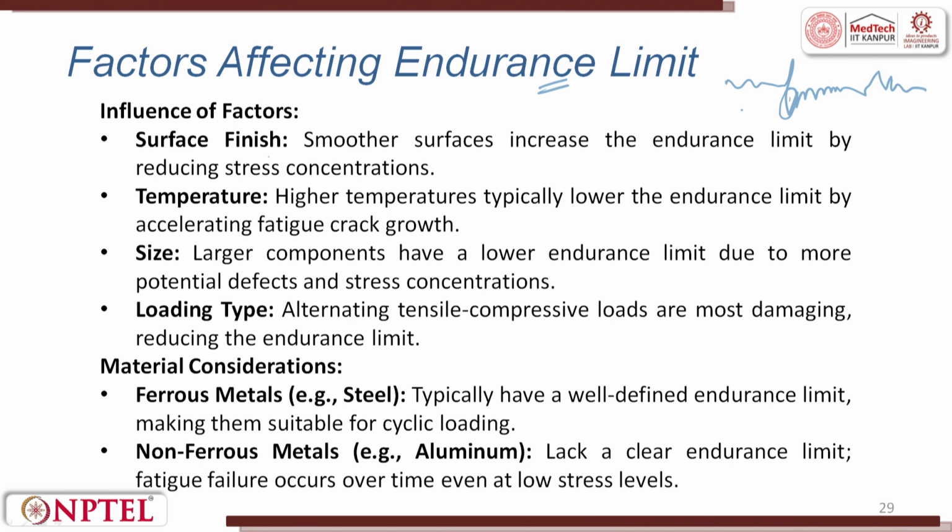For temperature, higher temperature typically lowers the endurance limit by accelerating fatigue crack growth. When you go to a higher temperature, the strength of the material slightly reduces, and the moment the strength reduces, the endurance limit for cyclic load also reduces.